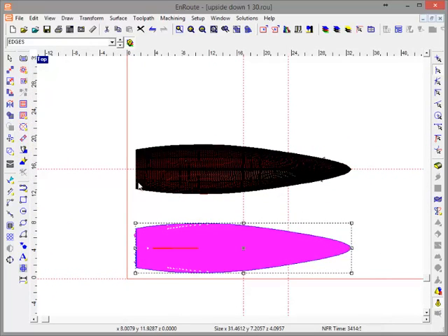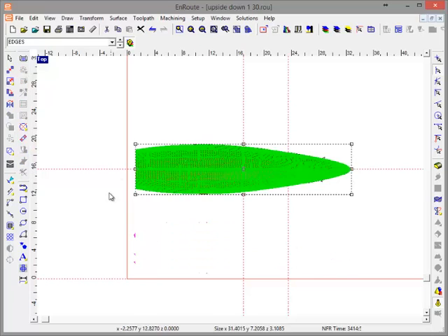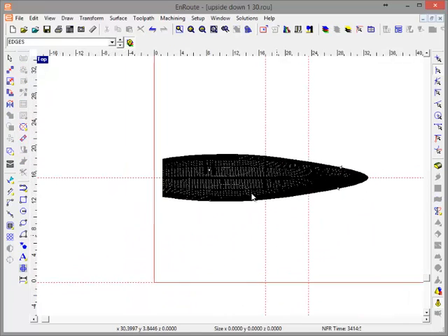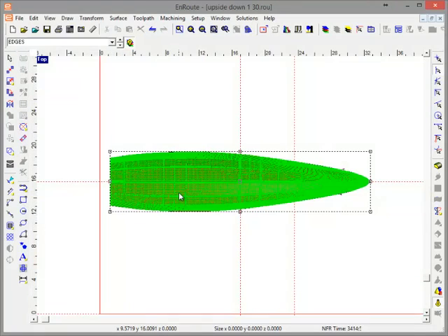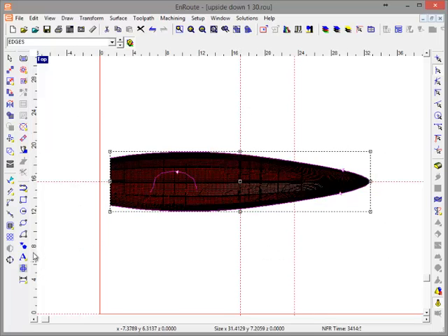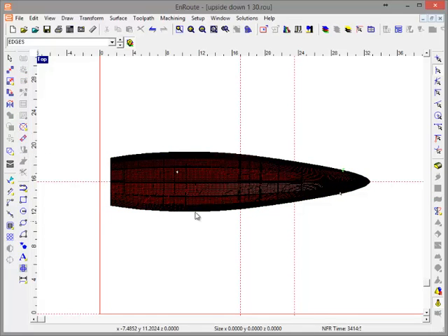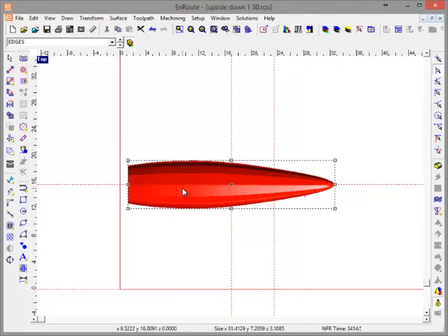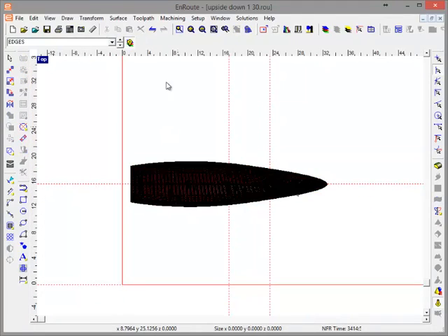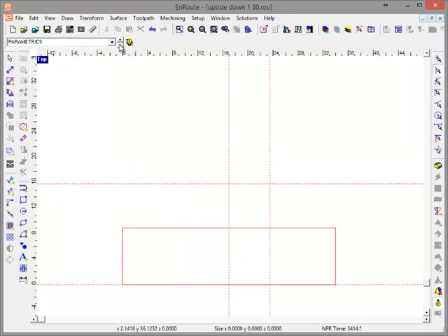So you need to get this version as a mesh STL that you can then import and do these things with. So the first thing you have to do is create a relief. And if you happen to have the outlines here, and we do, so let's make a closed shape here. I'm going to go to join contours. I know I have a rail here and a rail here that were open contours before, and now it's a closed shape. All right, let's turn off all layers here.